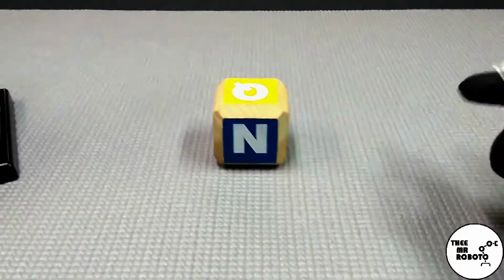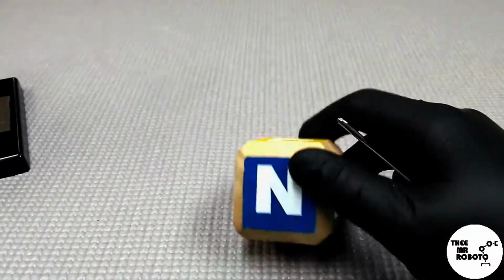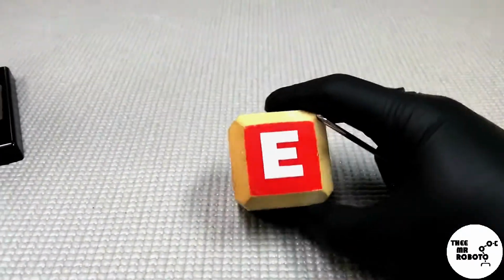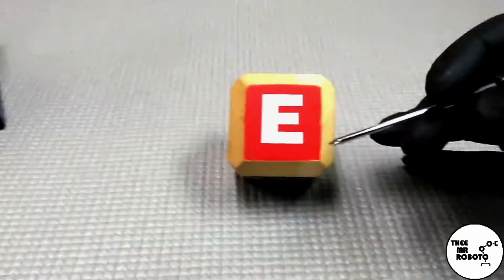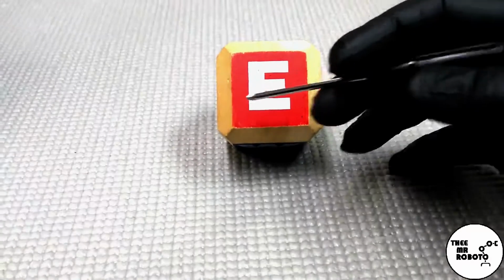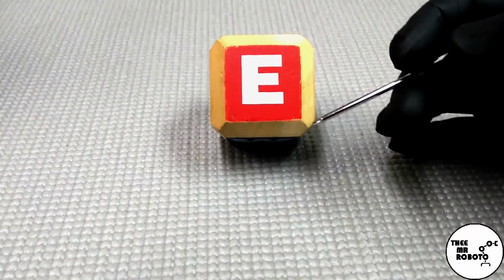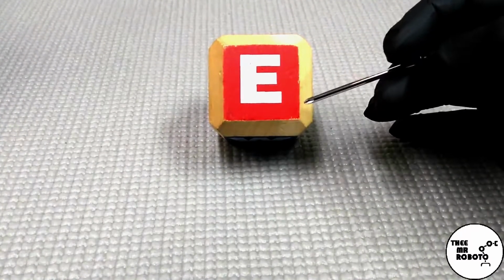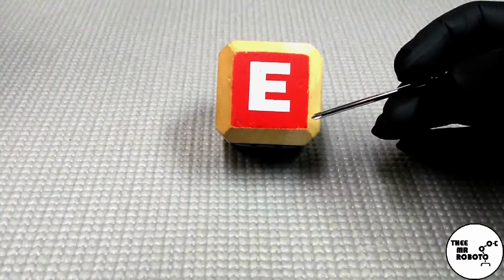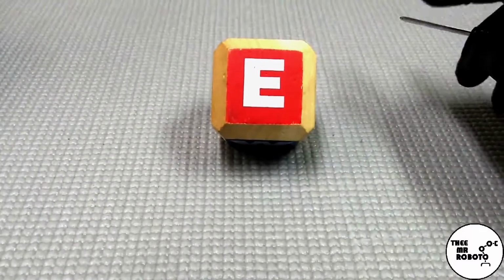So when you're setting up your coordinate system here on your fixture, you would set an X, a Y, and a Z, okay? And then this being on a 45-degree angle would also have an angular offset, okay?